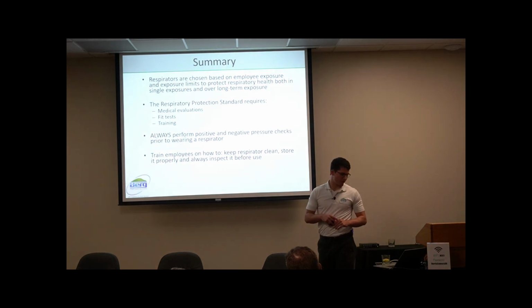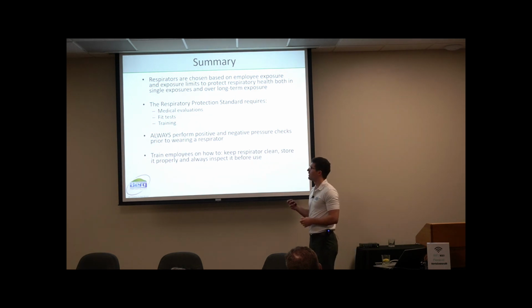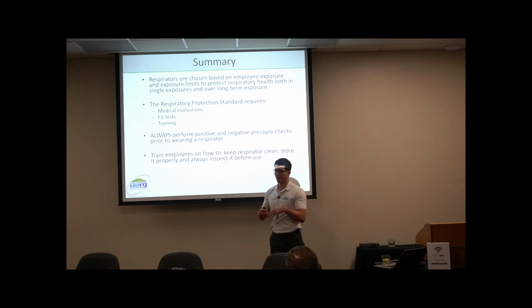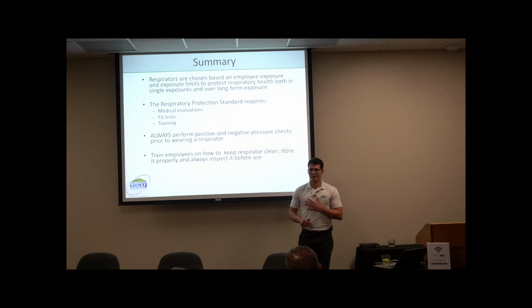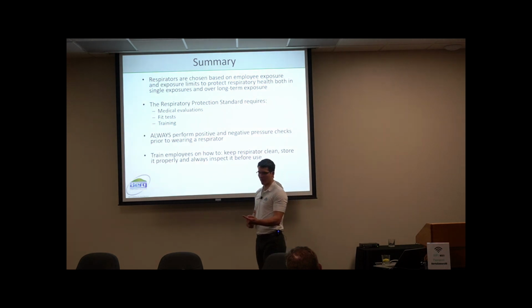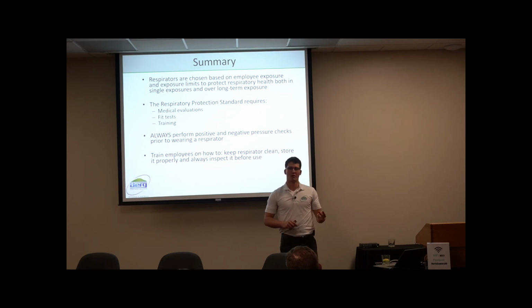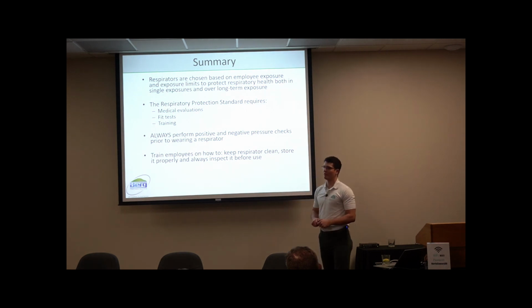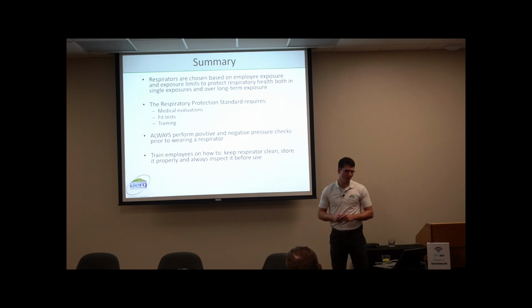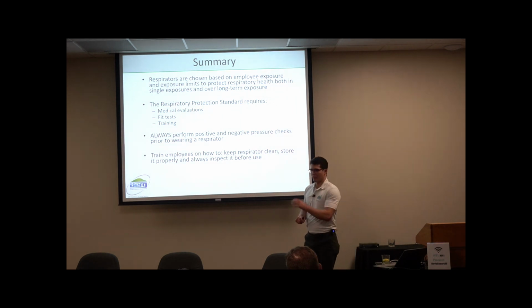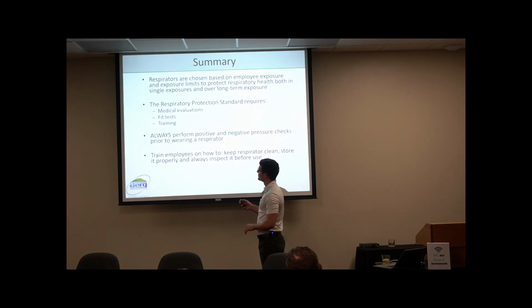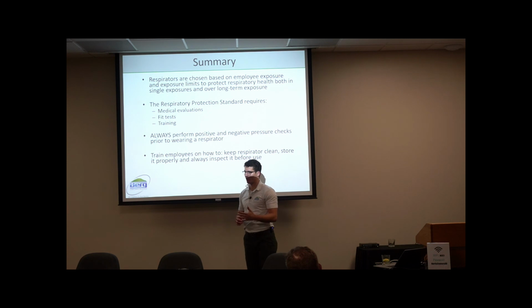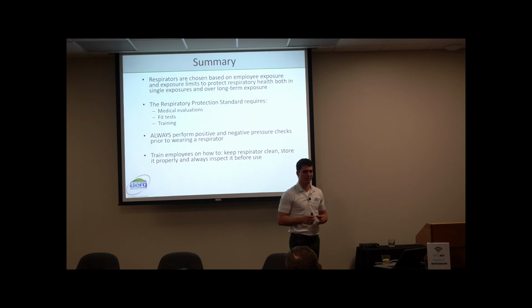Okay, the respiratory protection standard requires certain things. The things I would emphasize for the protection of them while they're wearing their respirator are your medical evals. How long can I wear my respirator for? And your fit test. Does it have a good enough seal to truly protect me while I'm working with that chemical? One thing that wasn't really mentioned in the presentation that I like to stress is make it second nature. Anytime you give somebody a respirator that has cartridges, make sure they do their positive pressure and negative pressure checks to make sure the seal is all right.